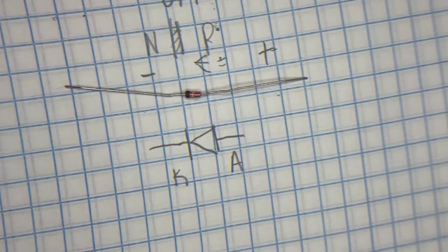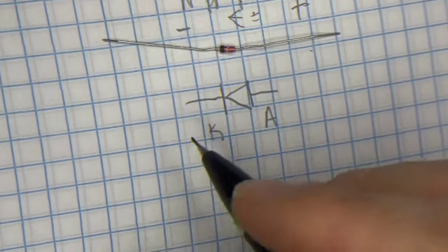So I'll show you on my tester. I'll run the junction through there. You'll be able to see what happens as the voltage goes up and what happens with the current, because it doesn't follow Ohm's law like you'd see with a resistor, where you get just a straight line going up. Instead, what'll happen is,